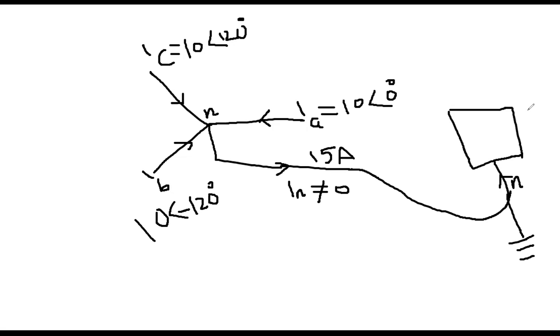And for example, you are the owner of this device, you might see that this device is gradually getting heated up. You don't know the reason. It looks like everything is fine in your home or in your system, but it is getting heated up. That could be the cause, because your neutral and the other neutral are bonded together and grounded together.